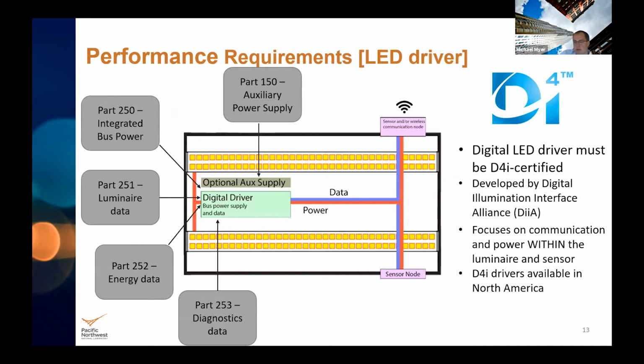So I mentioned this, this is really kind of it. I said it has to be D4i certified. This kind of image just shows what that means. D4i is just a collection of these standards, and it really focuses on communication within the luminaire. And what that is doing is it's saying, here, we're going to set up protocols for how you capture luminaire data and energy data and diagnostics data.